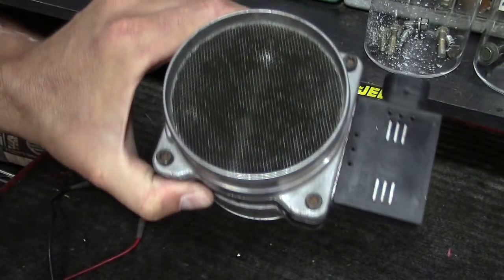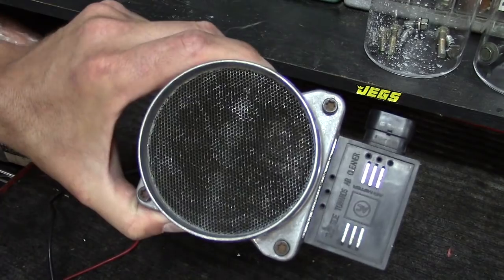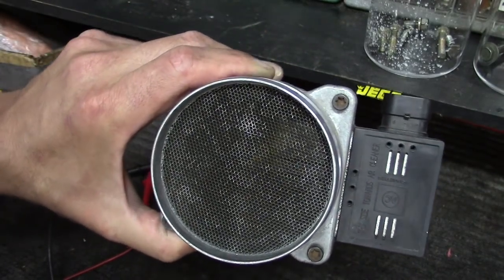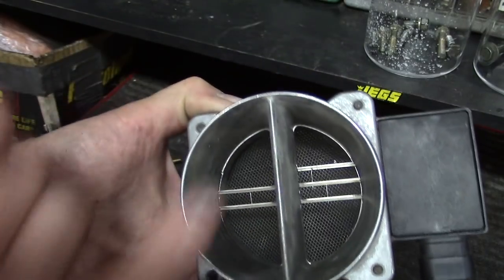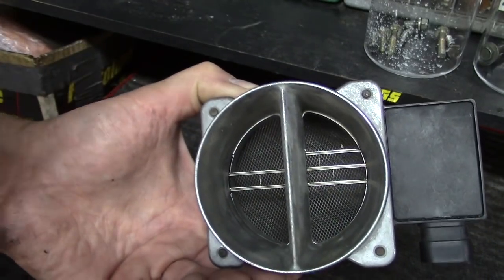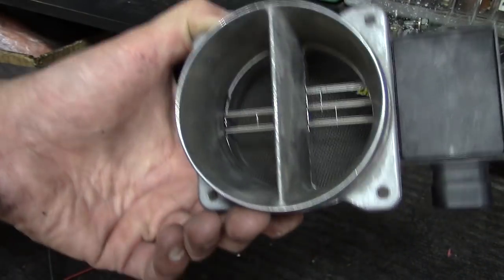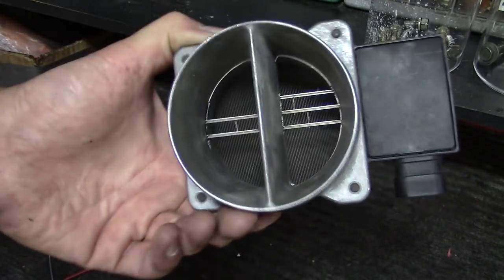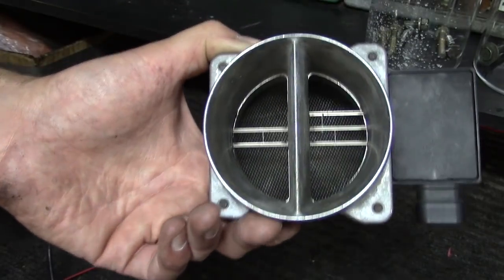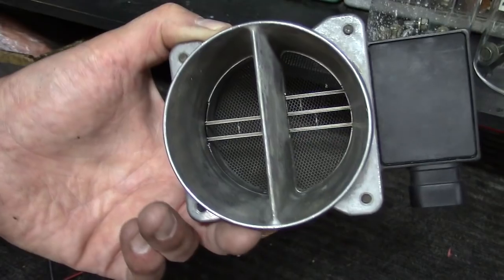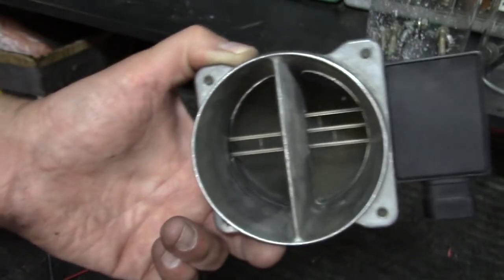Without the screen, you would have huge turbulence coming in there, and what would happen is more air would come into the engine than what is measured by the mass airflow sensors. Because of the variability of the turbulence in the airflow, you would lean out your car. Rule number one, if you are into performance, do not lean your car out. If anything, you want to side rich.